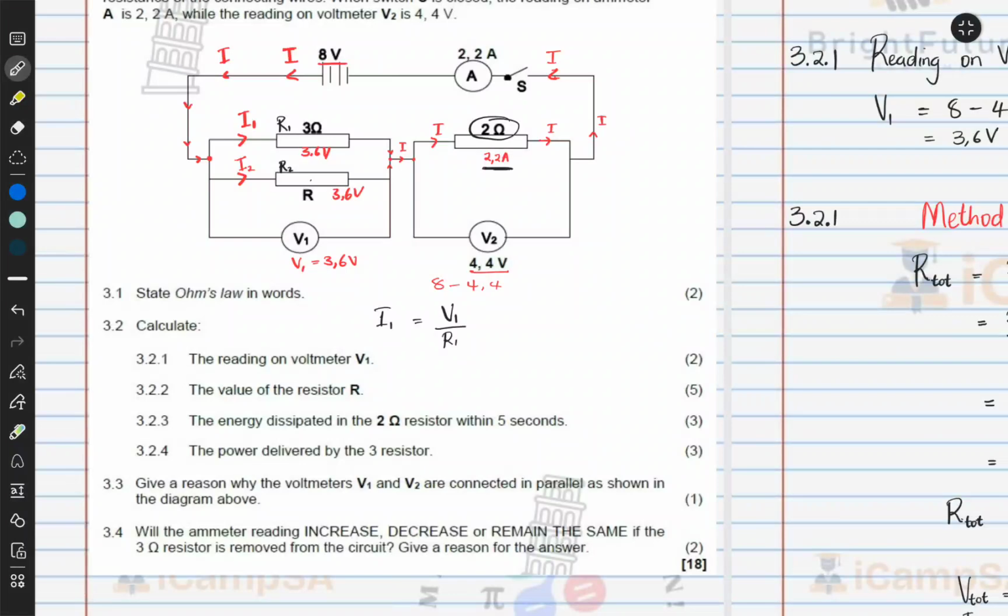It has an extremely high resistance, right? So the resistance is so high that if this thing was connected parallel to the resistor itself, it wouldn't be able to effectively measure, right? Because the current would avoid flowing through there, because current wants to flow in the path of the least resistance, right? So we usually connect voltmeters in parallel to a resistor whose potential difference we want to measure.